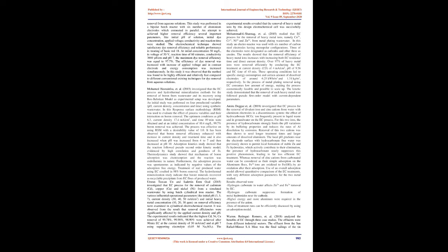It has been observed that boron removal efficiency was enhanced with increase in current density and treatment time, and it also increased when pH was increased from 4 to 7 and then decreased at pH 10. Adsorption kinetics study showed that the reaction followed the pseudo-second-order kinetic model, evidenced by high correlation and goodness of fit. Thermodynamics study showed that the mechanism of boron adsorption was chemisorption and the reaction was endothermic in nature. Furthermore, the adsorption process was spontaneous as indicated by negative values of the adsorption free energy. Treatment of real produced water using EC resulted in 98% boron removal.